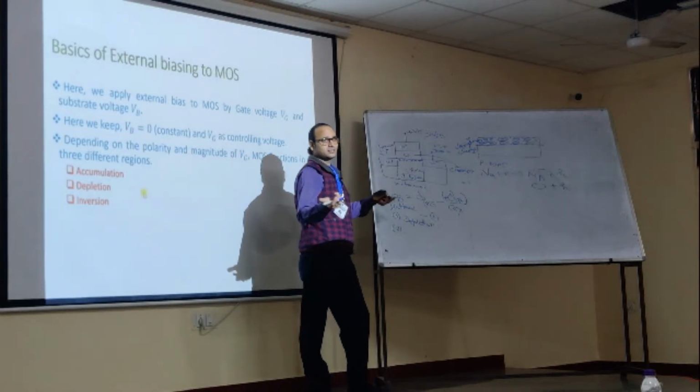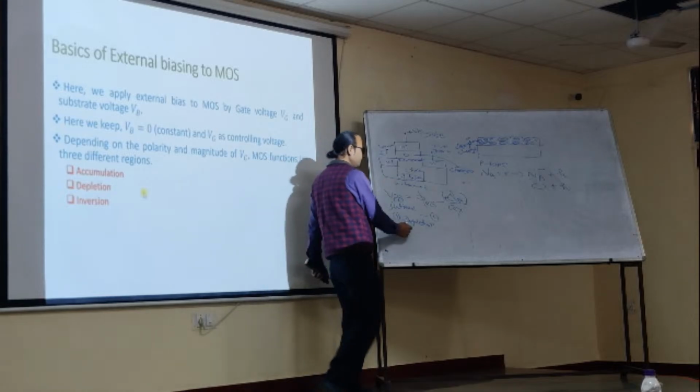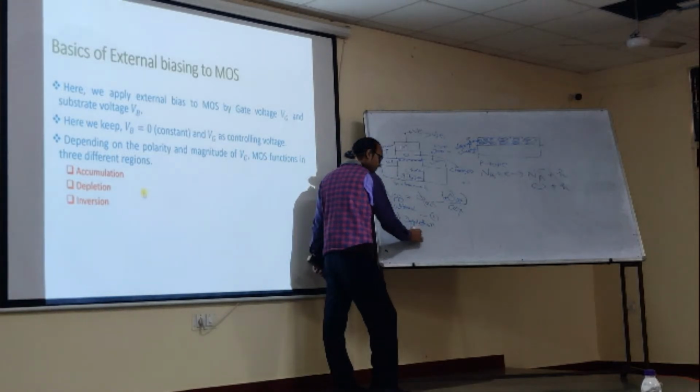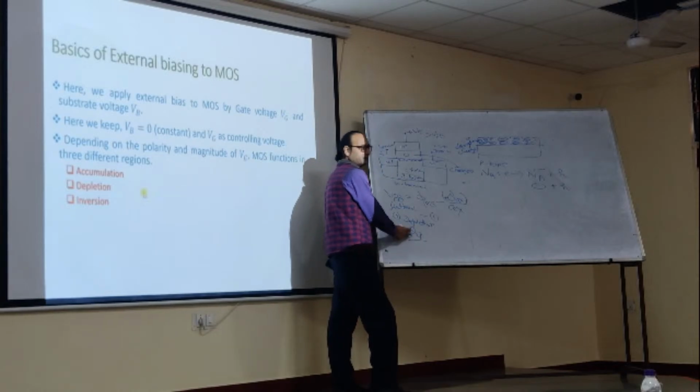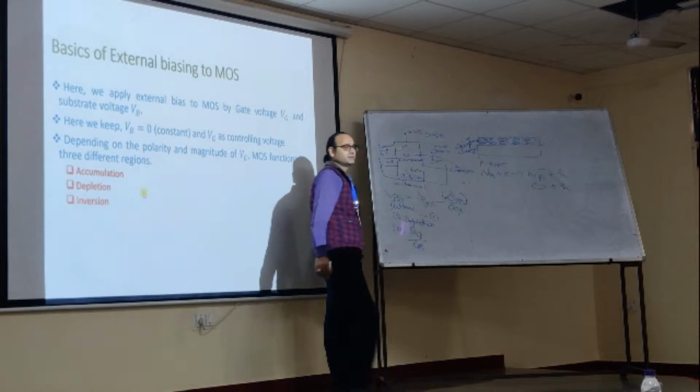So there will be another factor, that is, another voltage. We are not under inversion, still we are under depletion. So what will be that factor? We have to add this depletion charge, which I am representing by Qd, and again divide it by the oxide capacitance.